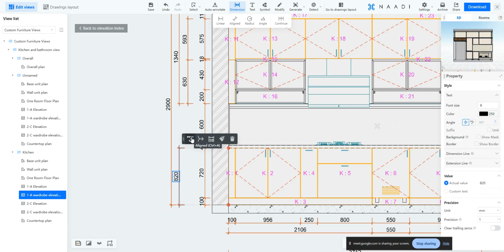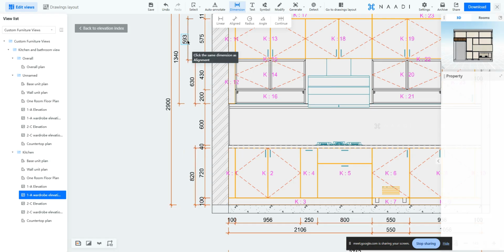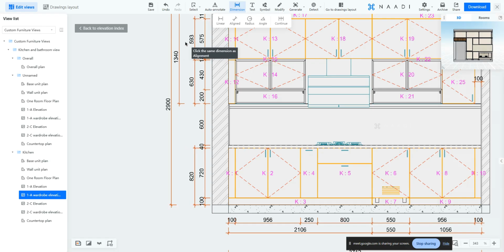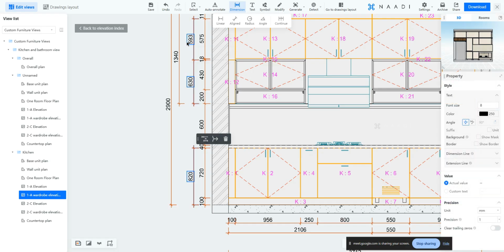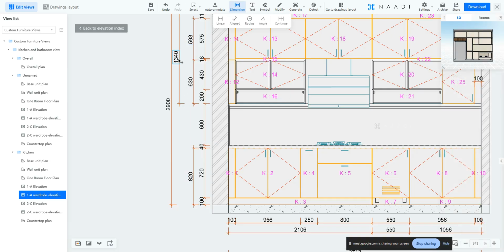Okay, if you use this, and now if you just select other dimensions, if you want to have them at the same level, you should be able to align all the selected ones. Now can you see all the selected dimensions will move as I move my cursor here. It is like I'm making it aligned at the same level. So this way, even if some dimensions are not aligned at the same level, you don't need to worry. You can use this align tool to precisely align it all together. Or like I said, you can also select one dimension and manually move it. It will automatically snap to the alignments. So that is also feasible here in that process. Okay, so those things could also be done.